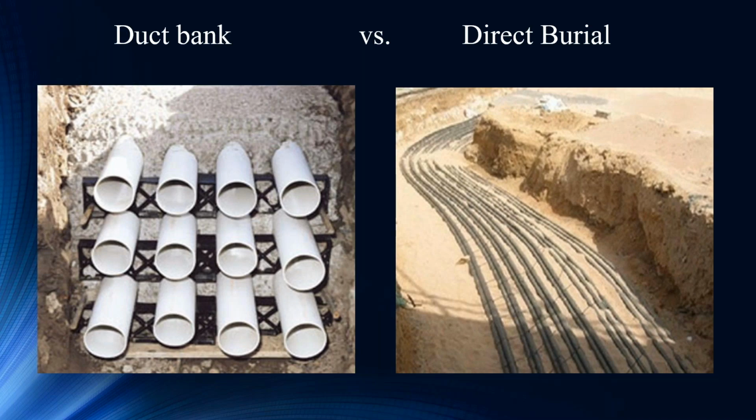Of the two methods, the direct buried raceway requires less capital for initial construction and has superior heat dissipation. However, maintenance and modifications of the line prove to be very costly. They require digging. Also, with this method, the process of locating faults becomes challenging.